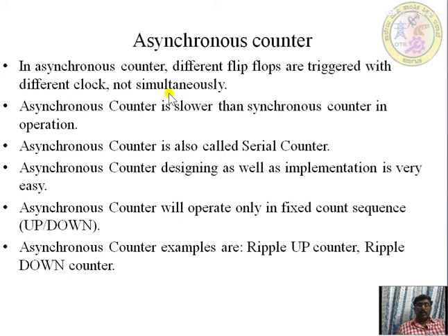Asynchronous counter: in an asynchronous counter, different flip-flops are triggered with different clocks, not simultaneously. An asynchronous counter is slower than a synchronous counter in operation. Asynchronous is also called a serial counter. Its design and implementation are very easy, though it is much slower.